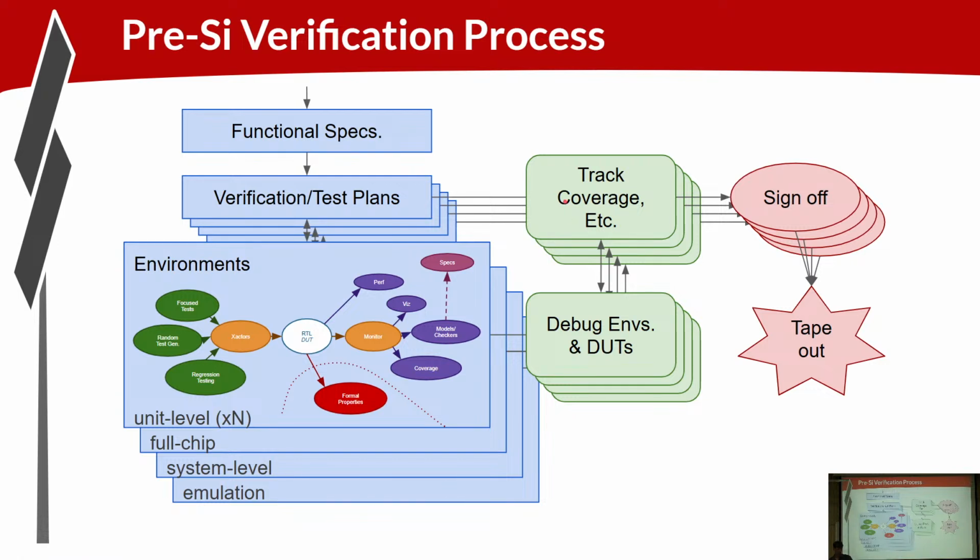So these are the models. This is the work. You're going to be using the verification plans to pound through all of the items in the plan and make sure you've got tests that achieve the desired coverage goals. So the test plans are going to incorporate a specification of what all the coverage is that each category of testing is trying to hit. And then the coverage monitors are making sure that you hit those cases. And that's giving you a level of confidence that you're exercising the logic, all the corners of the logic as best you can.